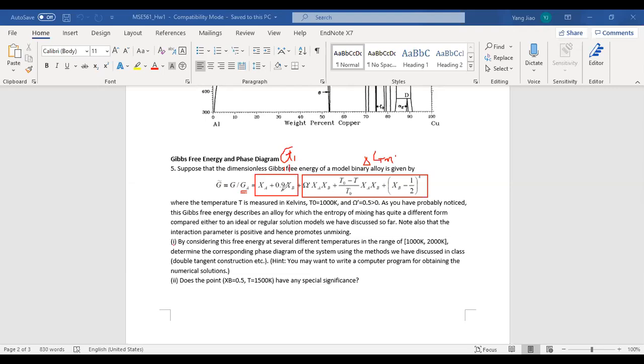It depends on the free energy of both systems, but I simply normalize the numbers with respect to a particularly selected energy scale. This is basically GB pure, the molar free energy for pure B, but measured with respect to the molar free energy of pure A. Nothing else than that. But we still have contribution from both A and B, and that is the G1 part.